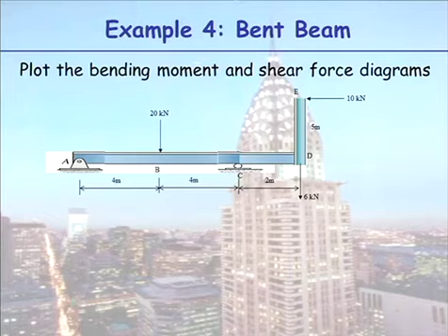When I was doing my member calculations for the truss, when I went across from one side, it all made sense. I got to the middle. When I went past the middle, I started getting things that should have been in tension being expressed not on the top and the bottom, but in the middle members. And I realised if I started from the other side, I would have had exactly the same thing.